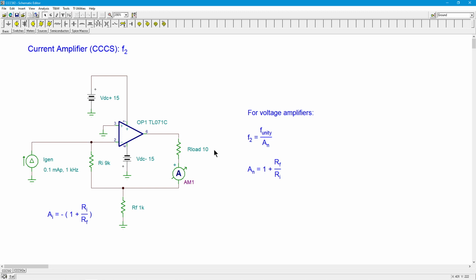It wouldn't make any difference. We're going to take an input current, multiply it by a certain factor, and that's going to produce an output current. The end. Within the normal limitations of the op-amp, right? You can't expect the op-amp to be pumping out 10 amps. It's not going to happen. But within those sorts of limitations, we just have this one equation, right?